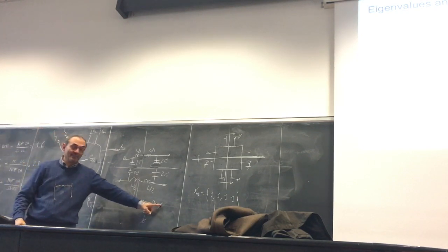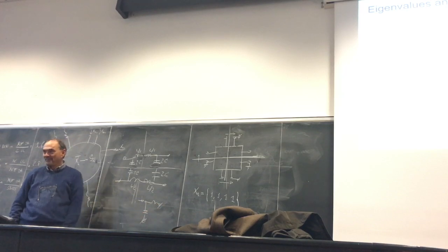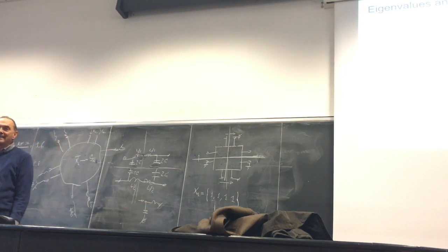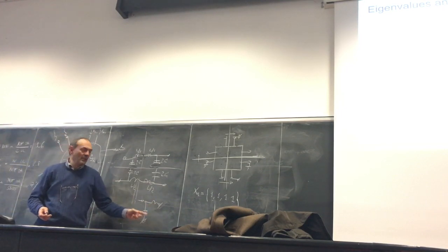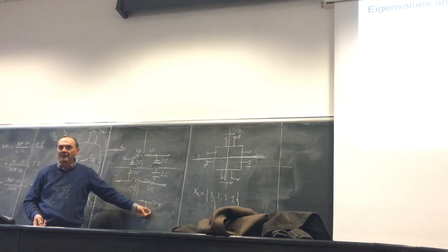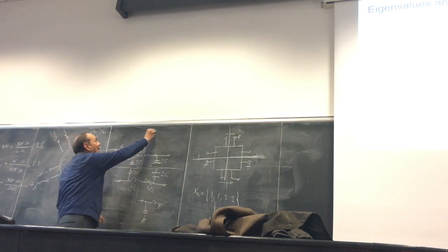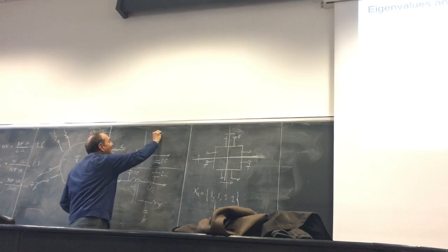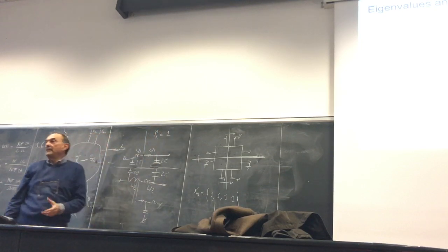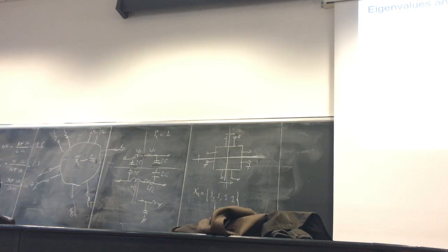This is open. This is open. Then, what is the impedance? Infinite. There is no path for the current to go to ground. So the impedance is infinite, and then gamma lambda is equal to 1, because it is an open circuit, no?